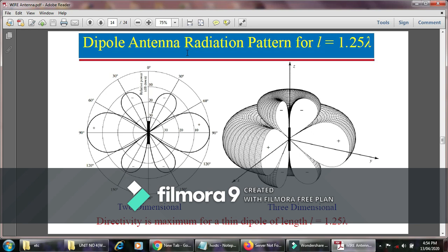That is why we consider, for the z axis, theta equal to 0, and relative power in dB in the downward direction, meaning 10, 20, 30, 40 in this way. The first circle is represented from minimum to maximum side. Then in the three-dimensional case, it will be a three-dimensional radiation pattern. The positive signs indicate the maximum radiated power or radiated signal from an antenna. Remaining all are side lobes having the negative